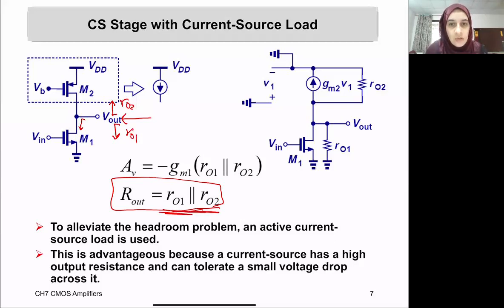Obviously, you can go back to the small signal model. And we said when you want to find the output impedance, you need to do two things, if you remember. The first thing, you need to short the input. And second thing, you need to apply a test voltage source from the output side. We call it Vx, having a current of Ix, and then your output impedance equals Vx divided by Ix.